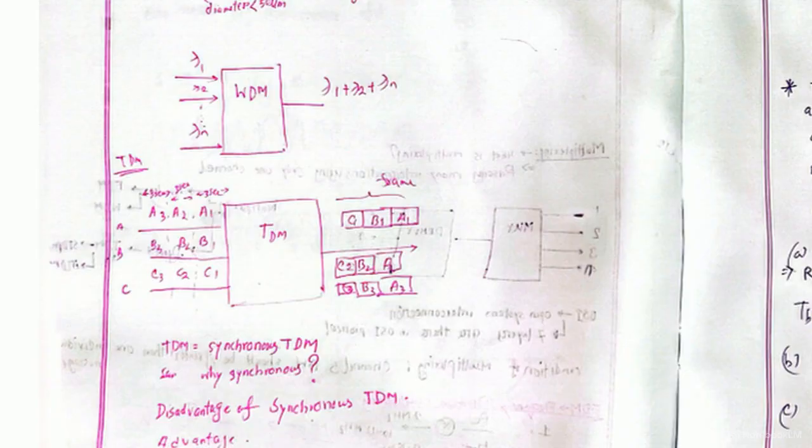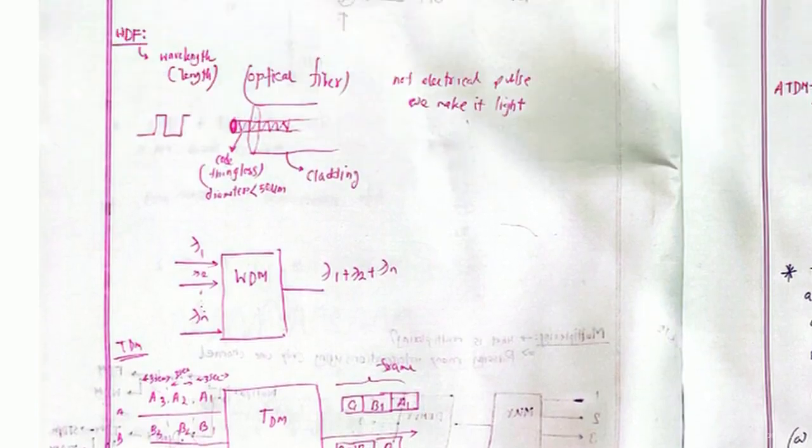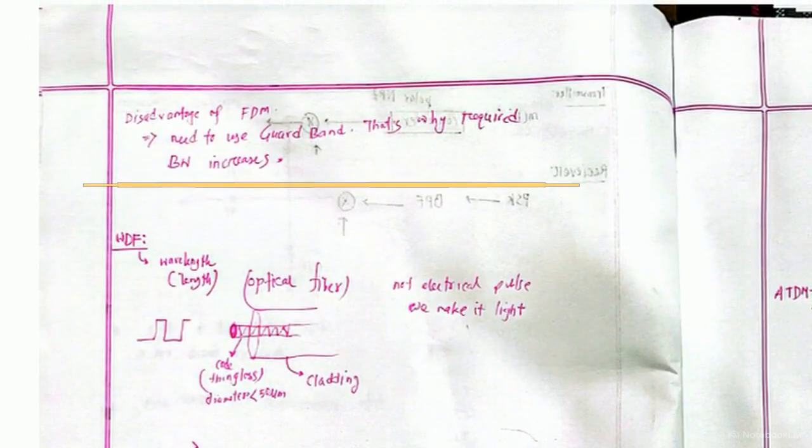Time division multiplexing interleaves multiple users by assigning each a dedicated microsecond time slot, while frequency division multiplexing carves the channel into narrow, distinct frequency bands. For more dynamic environments, engineers use spread spectrum techniques. This shift register diagram details the generation of a unique mathematical signature called a pseudo-random noise, or PN sequence.